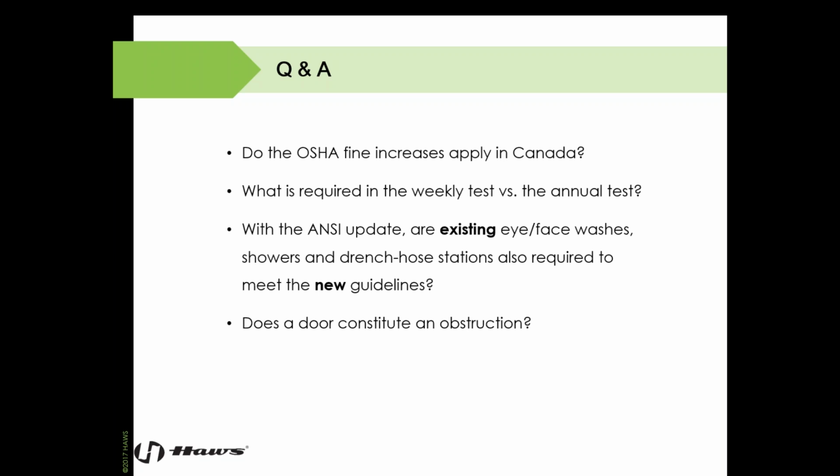A door is considered to be an obstruction where the hazard is not corrosive. One intervening door can be present so long as it opens in the same direction of travel as the person attempting to reach the equipment. And the door needs to be equipped with a closing mechanism that cannot be locked to impede access to the equipment. So in the 2014 revision, Appendix B states that a single step up into an enclosure where the equipment can be accessed is not considered an obstruction.